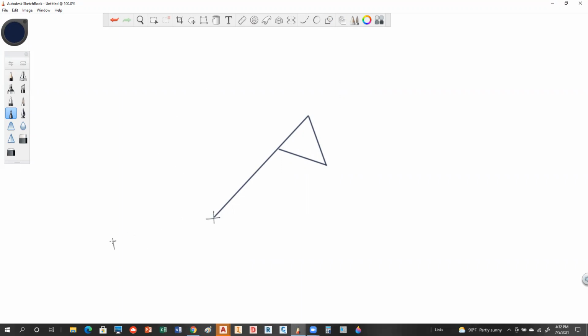But a lot of times what I'm going to do is do a base point that is on the object. And if that's the case, I want to make sure I use an OSnap. So you're going to have one base point. So you select objects first, then you select your base point. So then you have a couple of options. And one is to provide it the angle of rotation.